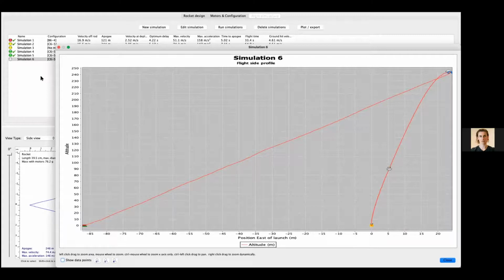And then we can see this is in low winds, remember. This is for 2 meters per second winds. When the parachute deploys, obviously the rocket isn't falling very fast, it's just drifting, and it'll be pushed by the wind back 100 meters with a net result of being 85 meters away from the launch site. So this is something you always need to look at when you're thinking where to launch. If you're wanting to launch in your backyard, this is probably not the rocket for it. Don't want to lose it over your fourth neighbor's fence.